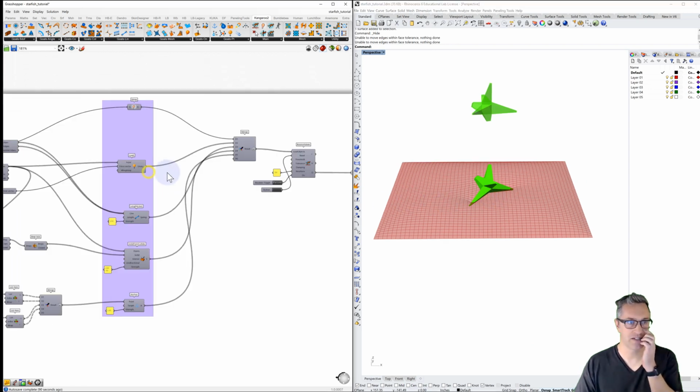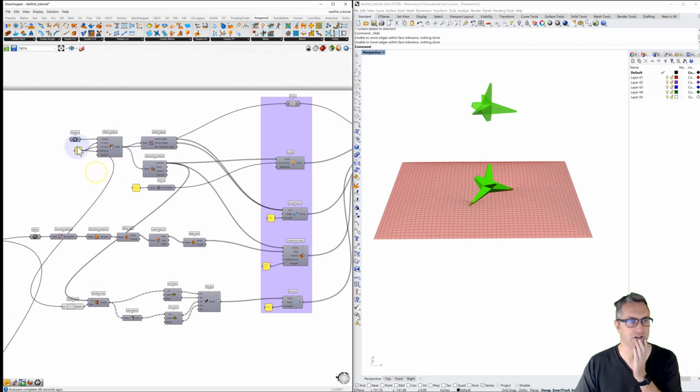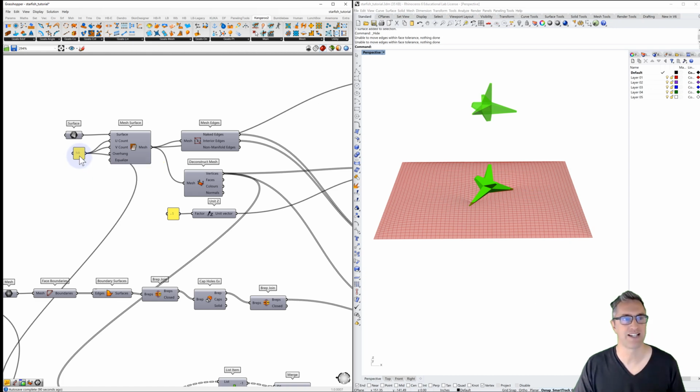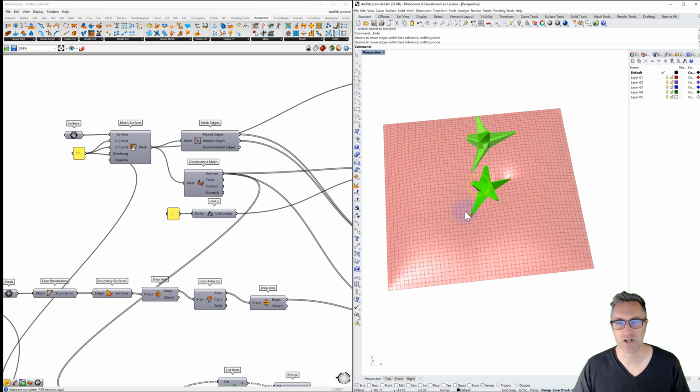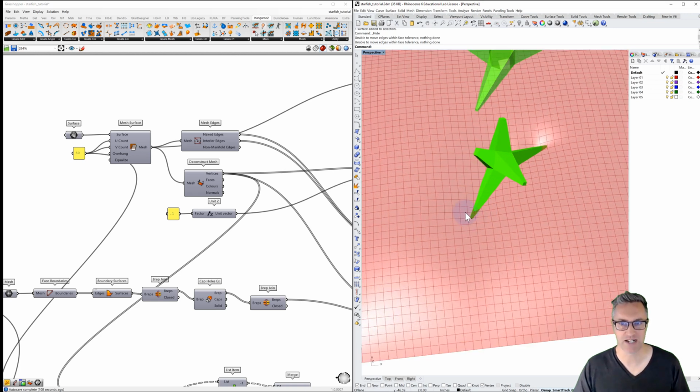the density of our mesh. I'm going to go from 50. I said when I made it that 50 was to try and go as low as possible. But if you really want to be specific, maybe we don't want that element puncturing through the surface. So let's go to 75. Your computer may not be too happy.